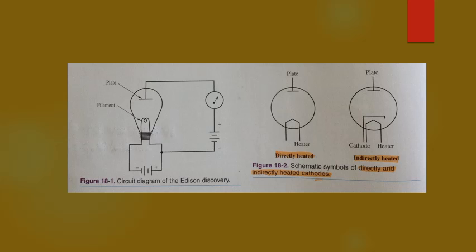The most efficient emitter is the oxide coated type. The emitter is a metal, such as nickel. On the emitter, a thin layer of barium or strontium oxide is formed. Because of its low power usage and high emission, this type of emitter was widely used in vacuum tubes for radios, televisions, and other electronic devices.